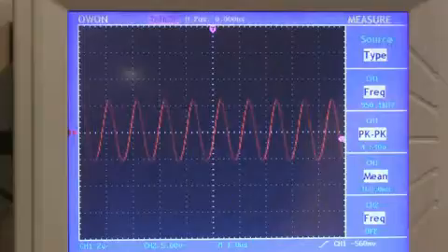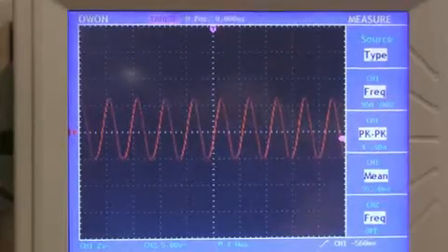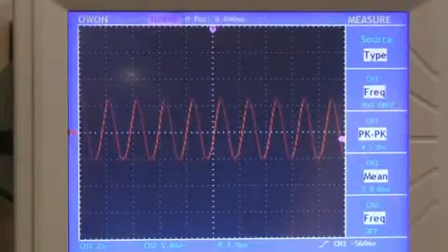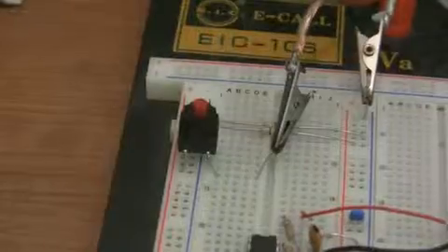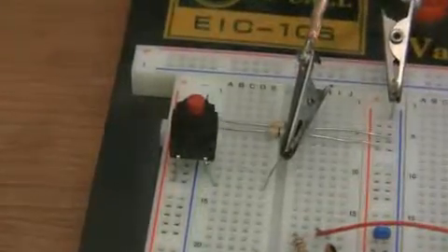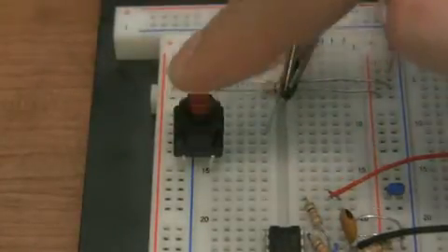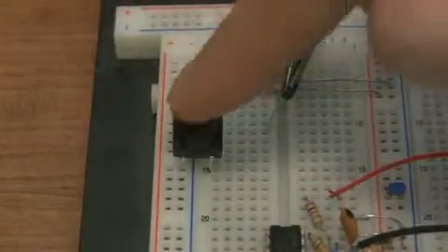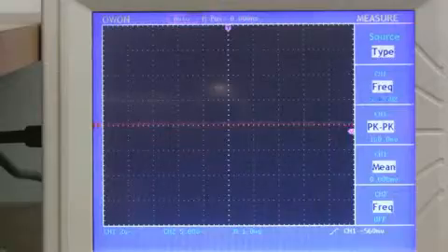At 950 kHz, you'll notice that the receiver goes totally silent. That's because it's detecting the radio waves that I'm transmitting instead of picking up random noise. Now this is where the fun starts. If I put a switch on the 9-volt supply line, I can turn the oscillator on and off, which will cause the waves to be transmitted in little pulses.